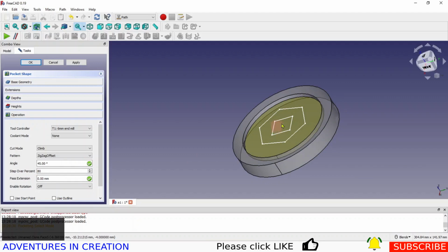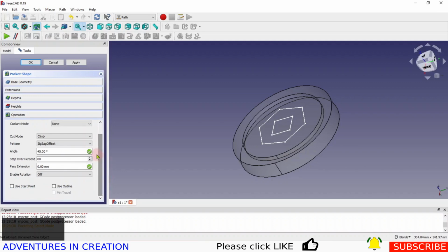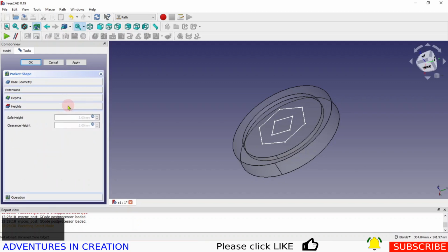That's 80%. You can do it 100%, but it leaves some lines there. I like 80% because it's just not as much stress on the tool. I've been doing some fairly aggressive ones where I've cut them deeper and 100%, and the tools just don't hold up very long. They're not expensive tools that I'm using, so your mileage may vary. And so this is my safe height and my clearance height.